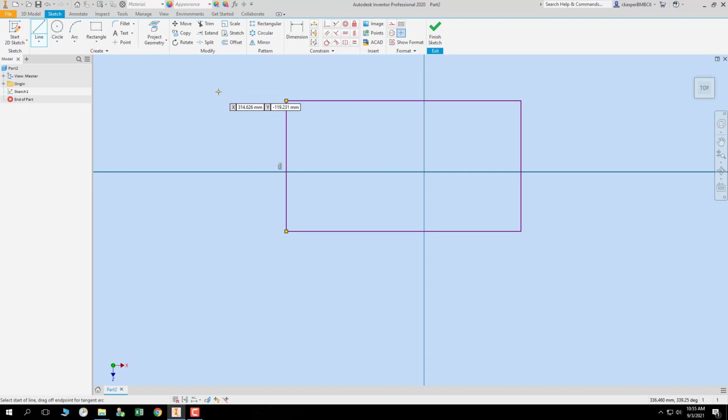Let's change it. There is a command. I'm going to show you a command over here and a command over here that will help you greatly. I'm going to show you the trim command. So, by the way, I'm still locked into drawing lines. Notice this line thing is still on. Even though I created an object here, I could draw. I'm clicking. I can still draw lines like crazy.